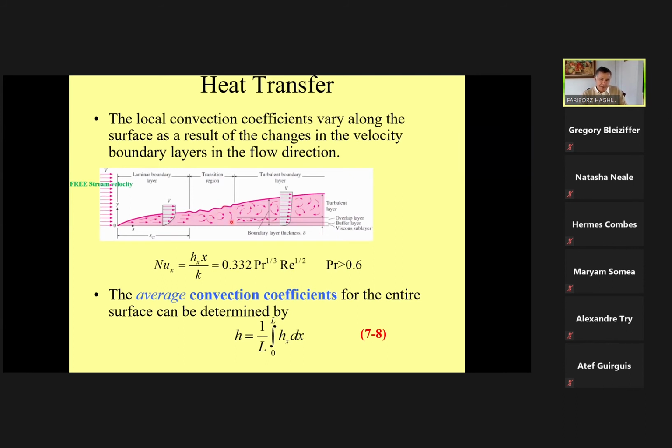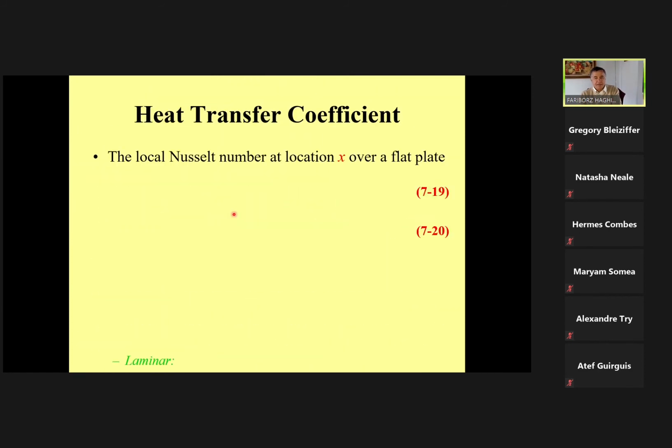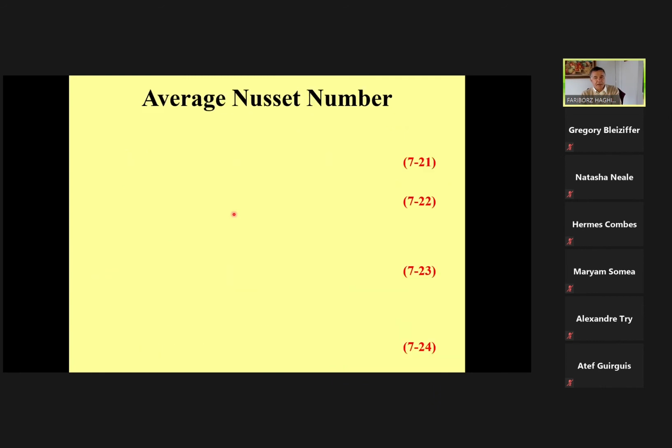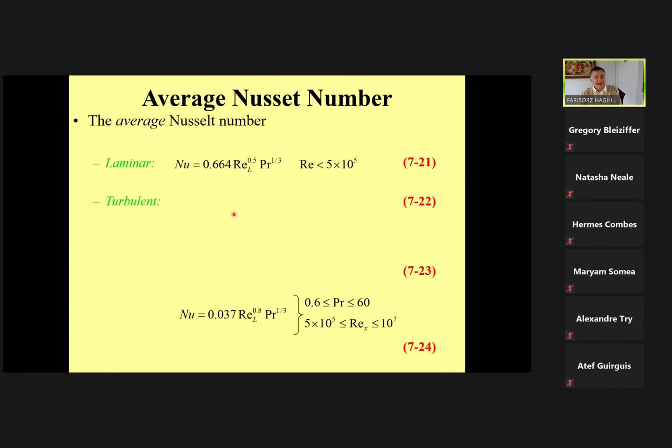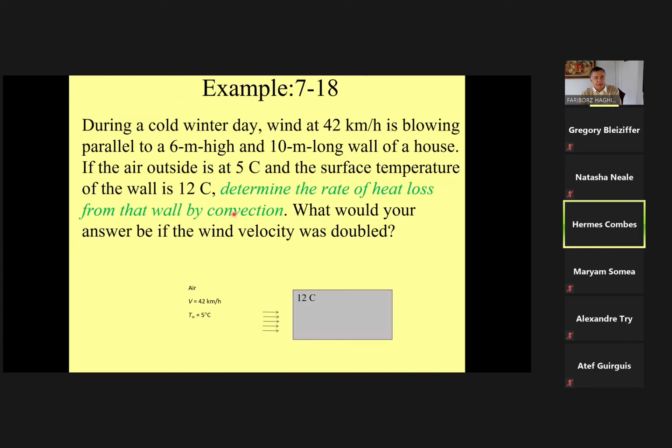Therefore, for the characteristics of the air, in this case the temperature difference is not that high, okay? In some cases, you're talking about 100 degrees and minus 20 degrees. Therefore, when they developed the correlation, they said, let's look at the physical properties of the fluid at the average temperature, not 5 or 12. So 17 over 2.